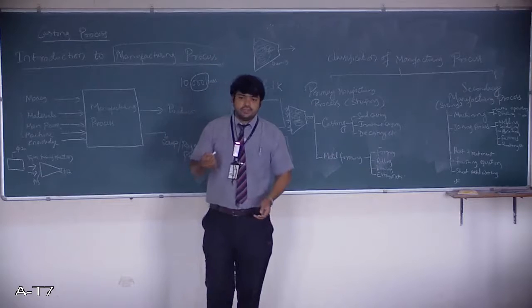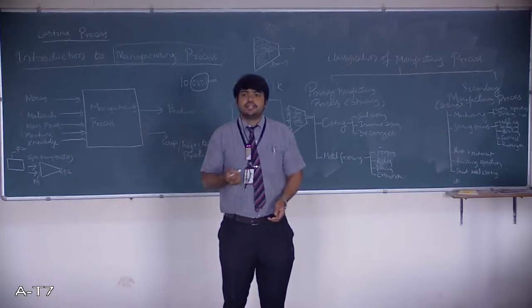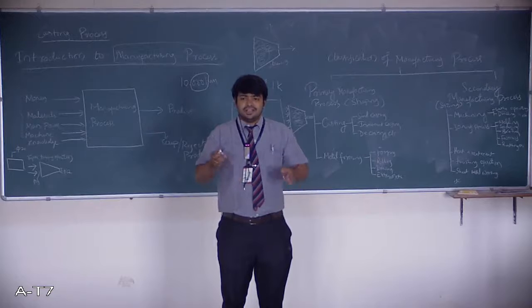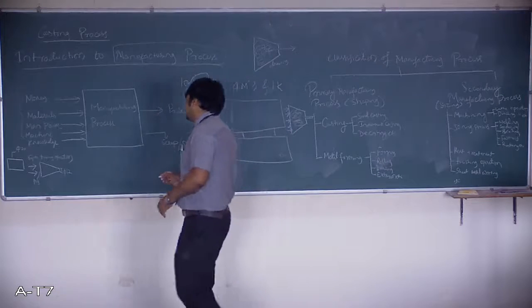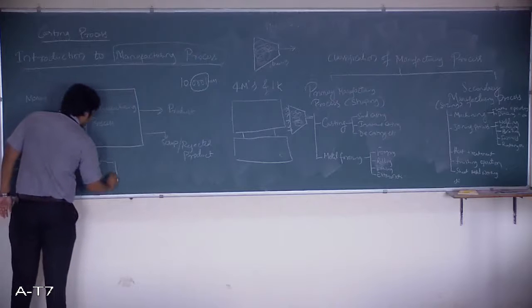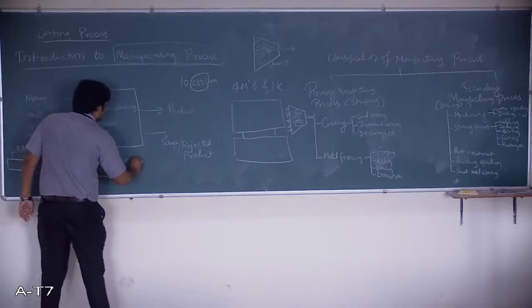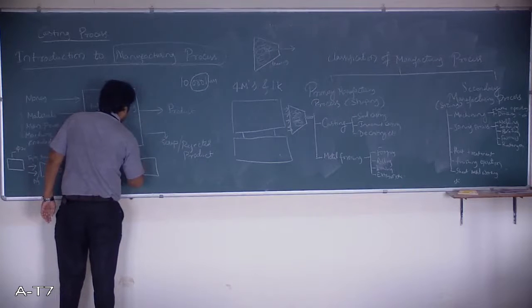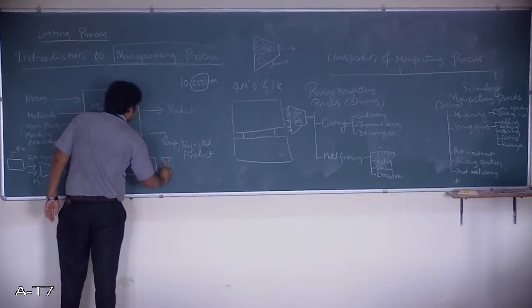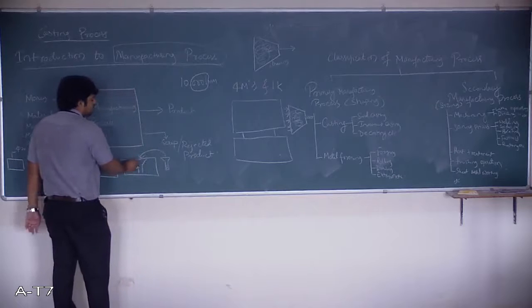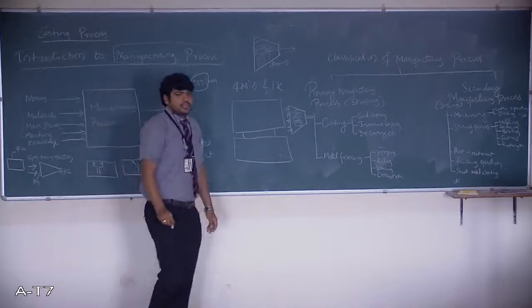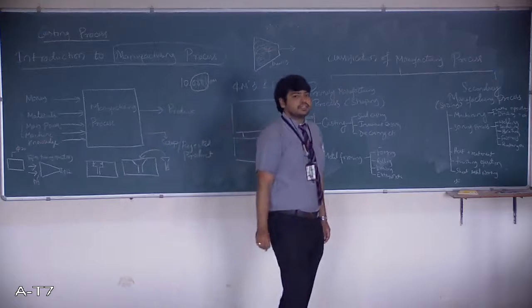We are going to enlarge a pre-drilled hole. That is what we call boring. We are going to enlarge only the head part of the hole like this. If this is the pre-drilled hole, then I am going to enlarge this part, or make a conical section so that this screw can be fitted inside this. This is called the countersinking operation. Like this, many types of holes can be drilled.